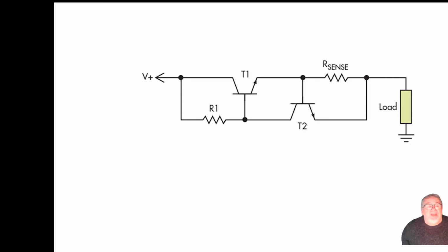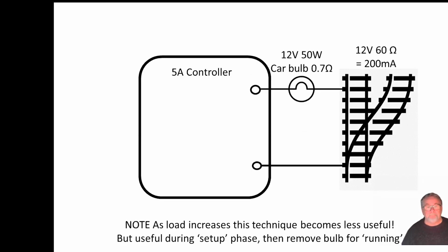If you were charging 18650 batteries, for example, you could use this circuit to simply limit the current into the 18650, and it'll limit the current to a sensible value until the voltage is reached, and then it'll charge at a constant voltage. Very, very simple current limiter.